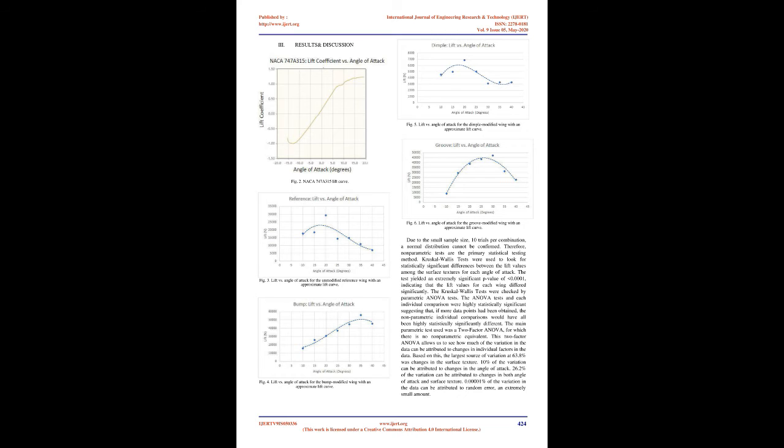The meshing area was defined to be 33.6 meters long, 12 meters deep, and 4.5 meters tall with increased refinement directly around the wing to allow for more accurate calculations. This was determined by Autodesk reference documents describing the process of modeling similarly turbulent and compressible flows.